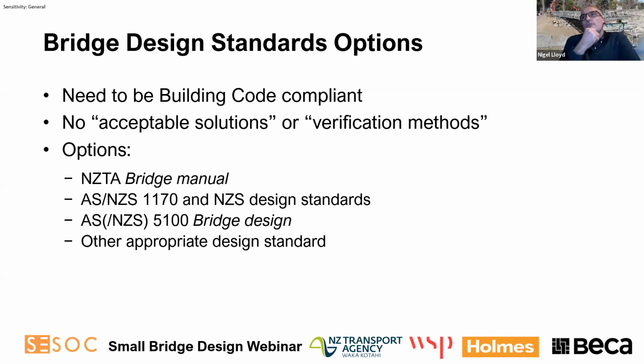First point of note, Geoff was covering this, that no matter what size of bridge, it needs in some form or other to be compliant with the building code. The building code is performance based, and we could talk for a long time about that as well. So without going into too much detail, it's there as a background document that you need to be working to. Unlike other forms of structures, there are no standard acceptable solutions or verification methods for bridges as a whole. There are for elements of them, but not as a whole.